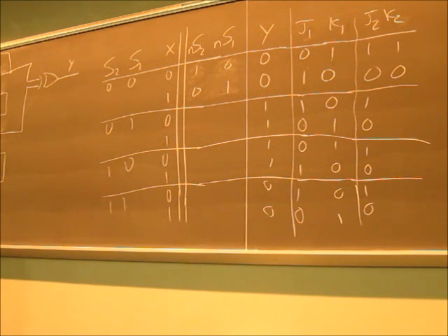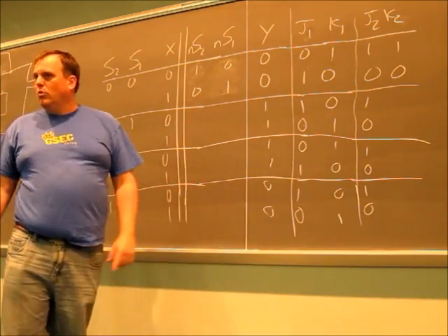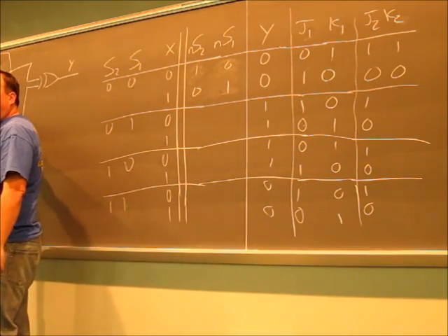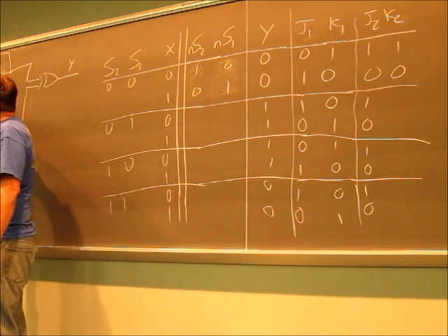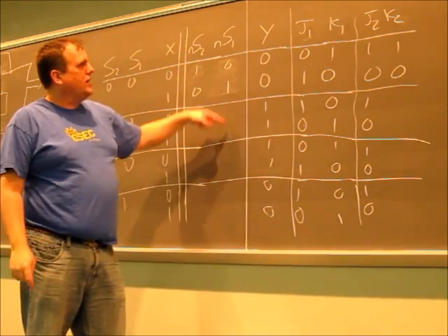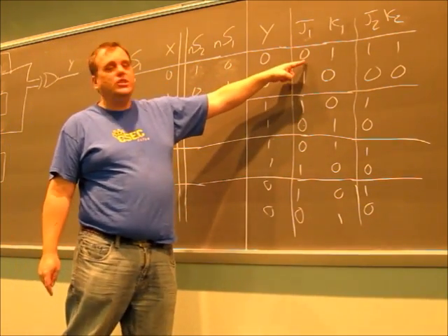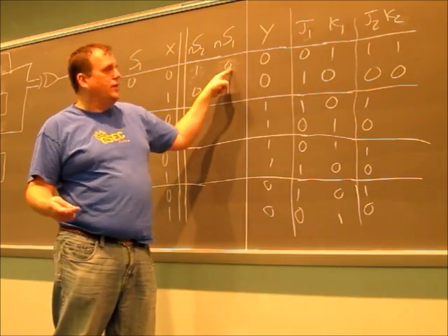Fair? Okay. So what that means is my next state, we're talking about state 1, because this is flip-flop 1. So whatever's on J1, whatever's on this line, which is this column, is the next state. And you can already see when we went through by hand without recognizing this, we came up with that. 0 gave us a 0.